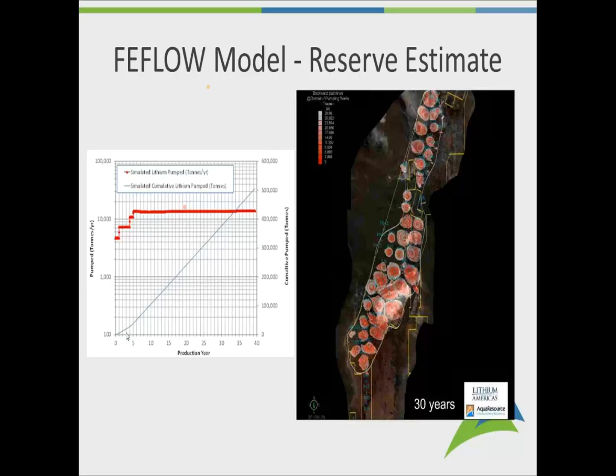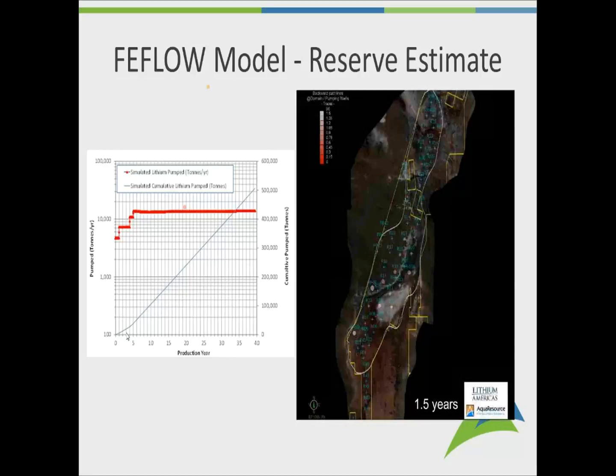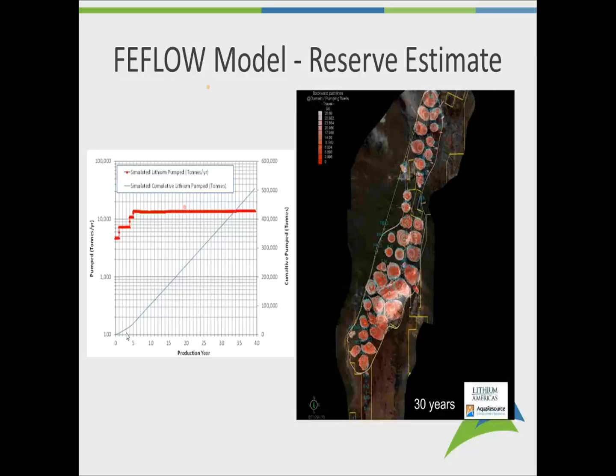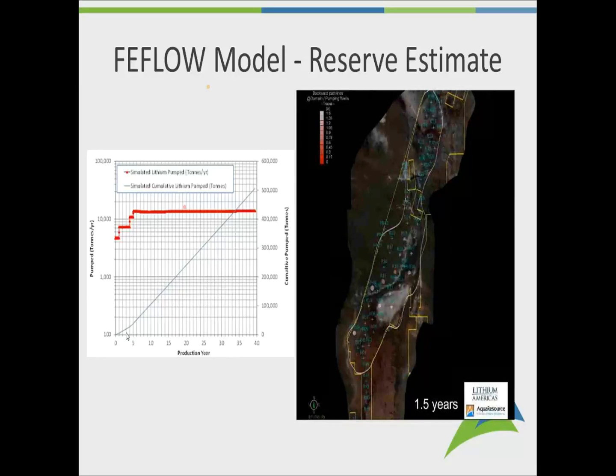Is that correct? Yeah. So the pumping wells were not pumped at the same continuous rate for the entire 40-year simulation, as Mark mentioned, and we worked with Mark on this project actually, and some of the wells get shut off earlier as their capture zone starts to reach the boundary. Other wells start with lower pumping rates and get turned on over the course of that. So there's a little bit of a trial and error to get to what we consider our solution for the reserve.